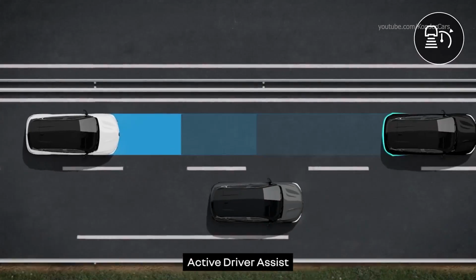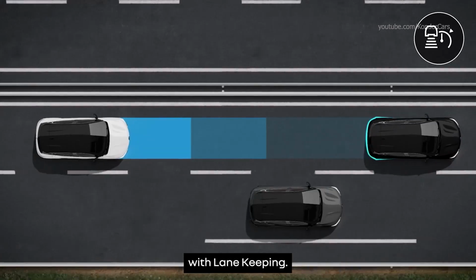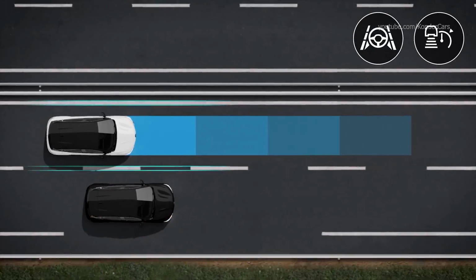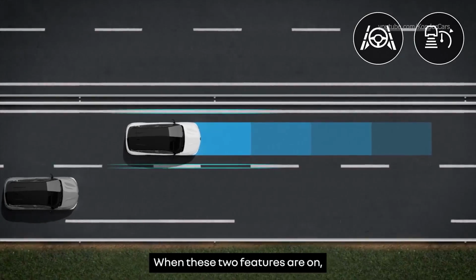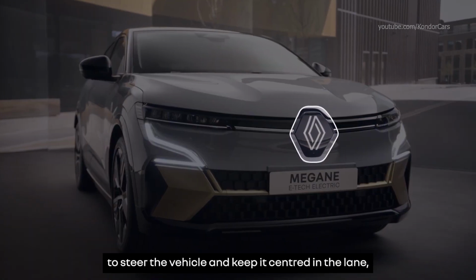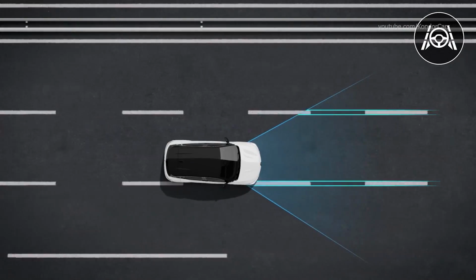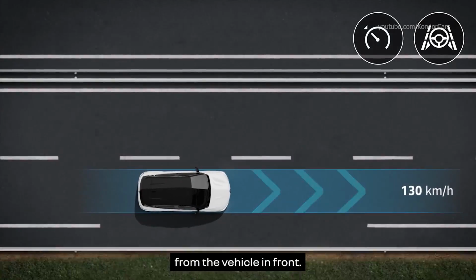Active Driver Assist combines stop-and-go adaptive cruise control with lane keeping. When these two features are on, the system uses information from the camera on the windscreen and the radar sensor in the front bumper to steer the vehicle and keep it centered in the lane, maintaining a cruise speed and a following distance from the vehicle in front.